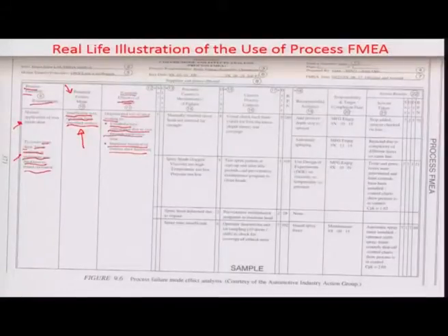You always find squeaky noises when doors open in old automotives. Let's say after 5 years, 6 years of drive, you always find that the improperly lubricated door hinges may result in some very strange, eerie kind of squeaky noises while opening, which may not be very well appreciated by the user or the customer. So these waterlogging problems would result in such kind of failure modes. The other most important potential effect for the failure could be related to the appearance problem due to rust coming up from the door outer.